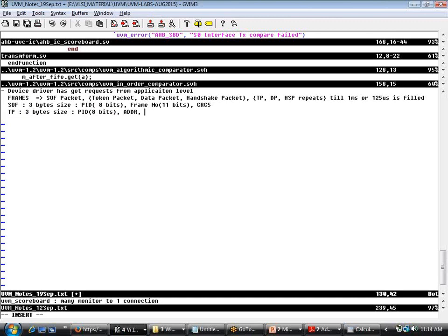The host will broadcast data to everyone. My device should detect whether this is data for me or not. This address will help it detect that. How many bits is this? 7 bits. I said that during enumeration, the host assigns a 7 bit number to each connected device. The device will compare this 7 bits with whatever 7 bits it has stored. Then it will know whether this token packet is for it or not.